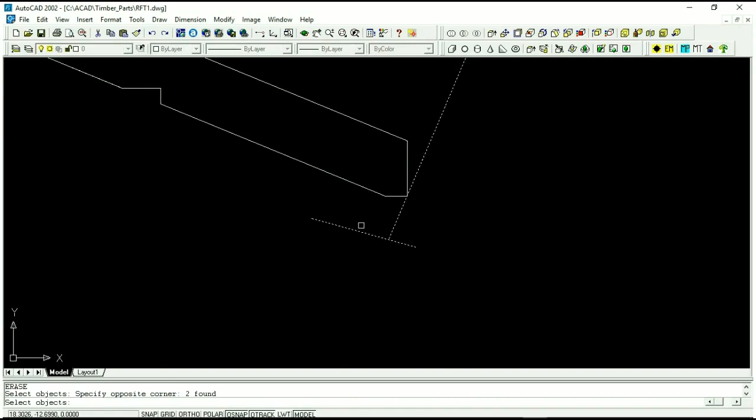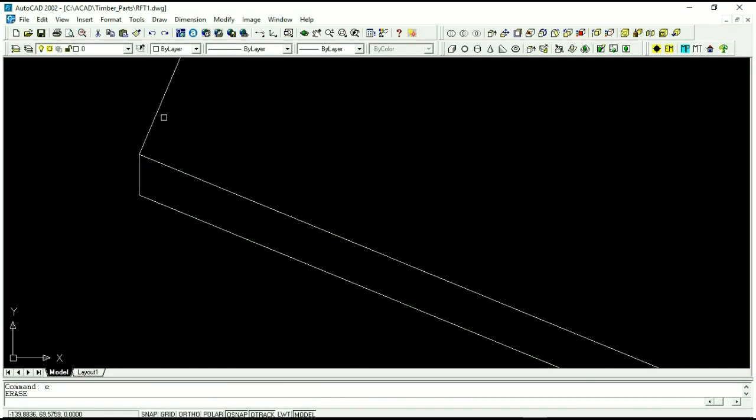So when I do material utilization, let's say I build the 3D model, I export the part names, and then I run them through some other Excel files or Excel macros, and it does a material utilization. It knows that it needs a 16-footer to do that rafter. And if it had like a 12-inch 2x6 that it needed for blocking, it would combine this part with that part and give the manufacturer or the guy out in the field a list of parts that go on each length of lumber.